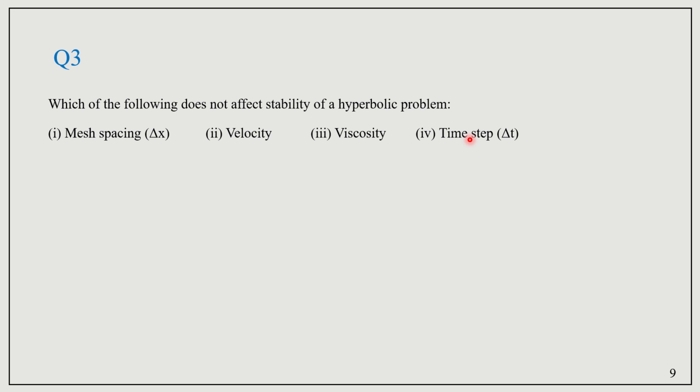What we are trying to capture is with what speed the information is being transferred across the cells, across the grids, with respect to time. If it is traveling fast, or if it is traveling a far distance, we will be missing out certain information, so the system will go unstable. That is how we control the stability of a system using the Courant number and so on.